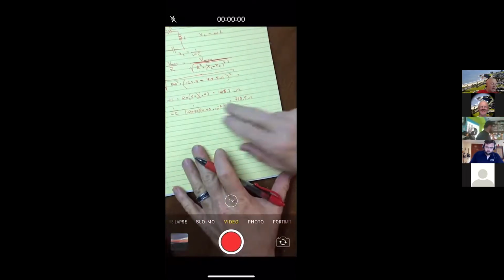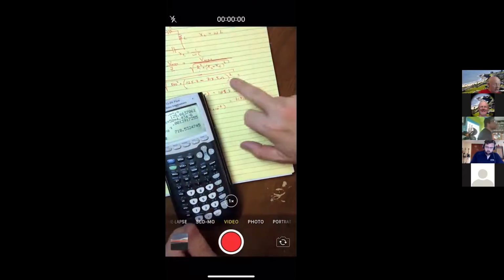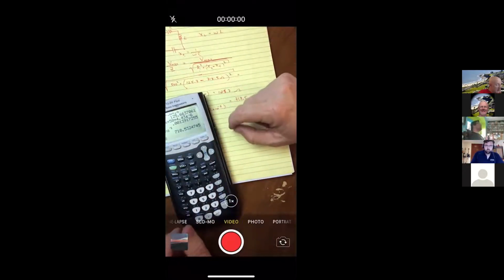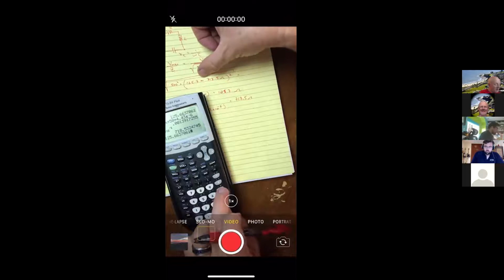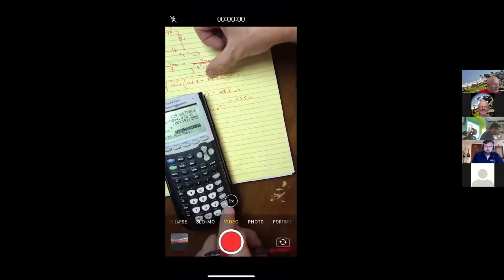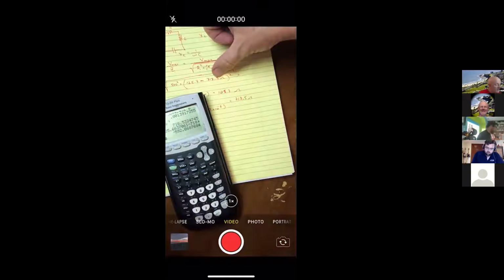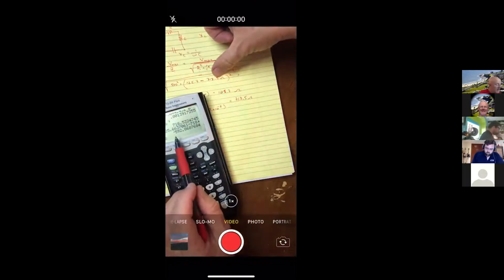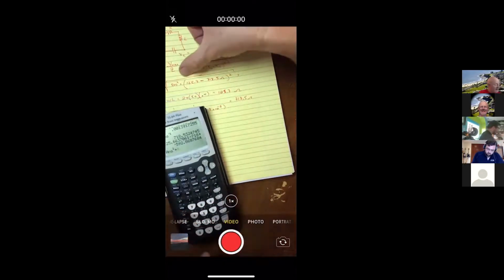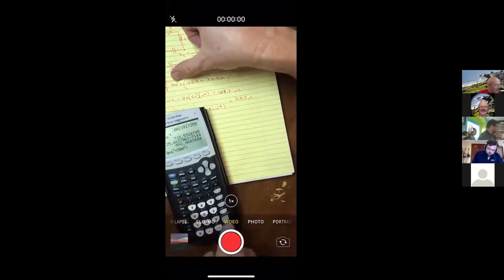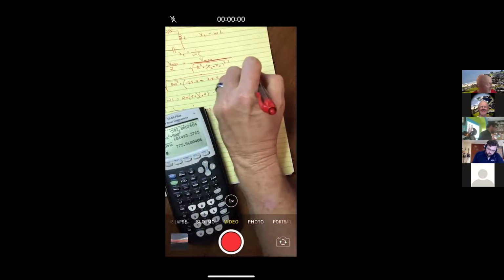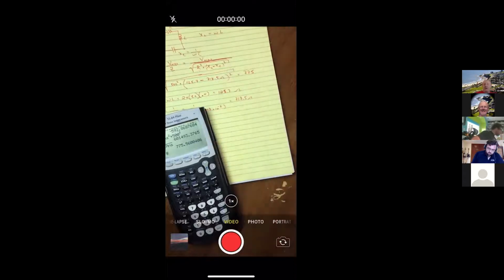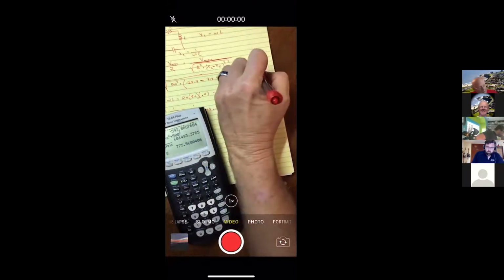All right, so now I can actually do this calculation and get the impedance. So I think I will go up and grab that 125.7. I will subtract off the answer I just got. And so that's about a negative 592. Let me square that and then add it to 500 squared. And then finally taking the square root of all of that leaves me with an impedance of 775.6.